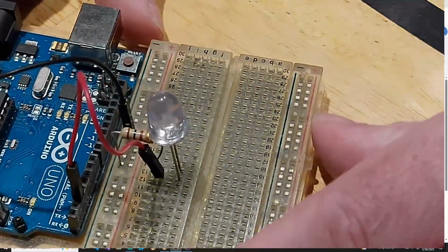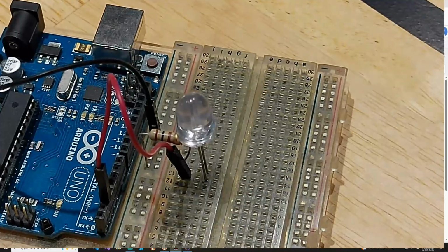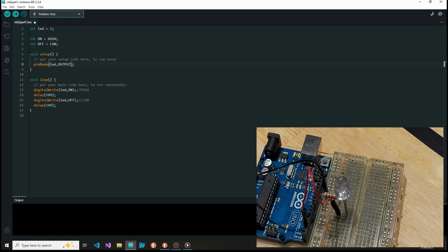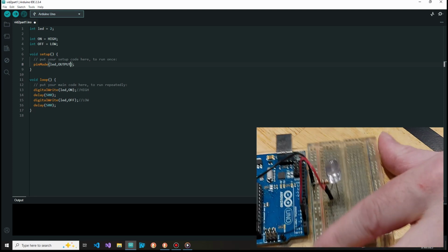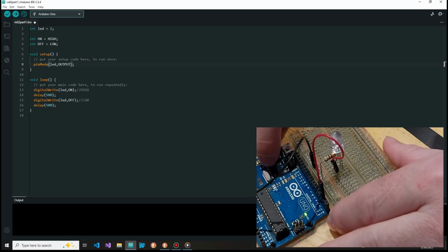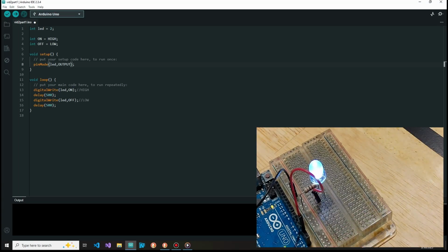So now let's jump back over to the Arduino and pull up the IDE again, and we will now plug in our Arduino. I ran a test run here, so it's going to start blinking. But now, if you look back up on the screen, you can hit your drop-down box here, and it will say Arduino Uno. Mine says COM4. Yours is going to say something else. Click on that, and just like the last video, it will confirm that it has been connected.